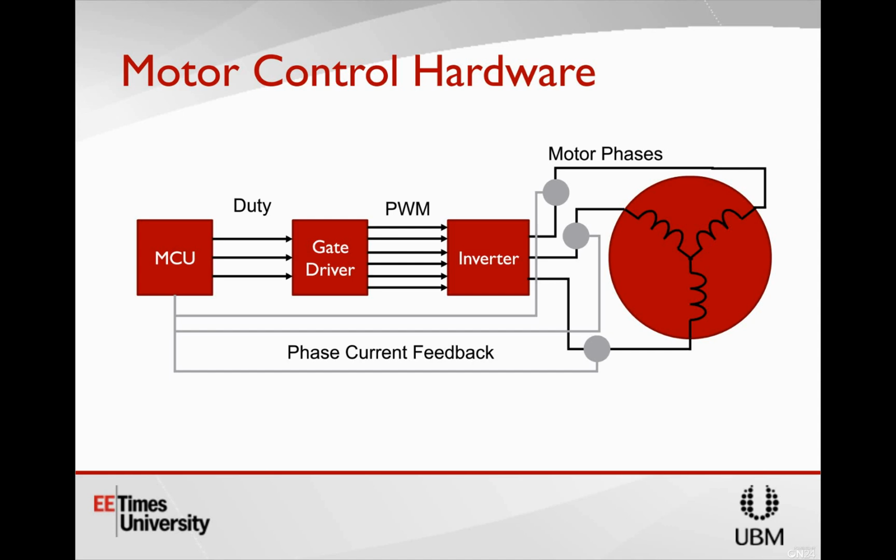And what we said yesterday when we were discussing trapezoidal or six-step control is that these sensors are really the least robust part of the system. And in FOC control, that's even more critical. Encoders are notoriously much more fragile than even Hall effect sensors. It adds additional connectors, additional power supplies. It adds a lot of complexity and risk into systems. That's why there's a lot of work on sensorless algorithms to be able to remove this dependence, because it can make it very difficult to have a high degree of robustness on your system.